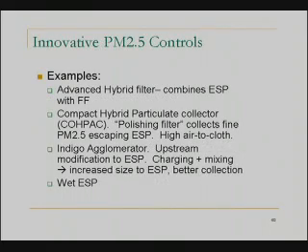The second type mentioned in the contract report was innovative PM 2.5 controls. This is not just changing the device in a minor way, but entirely different technologies. For example, COHPAC, a compact hybrid particulate collector, is essentially a polishing filter with a relatively high air-to-cloth ratio that can collect fine PM 2.5 downstream of an existing electrostatic precipitator.